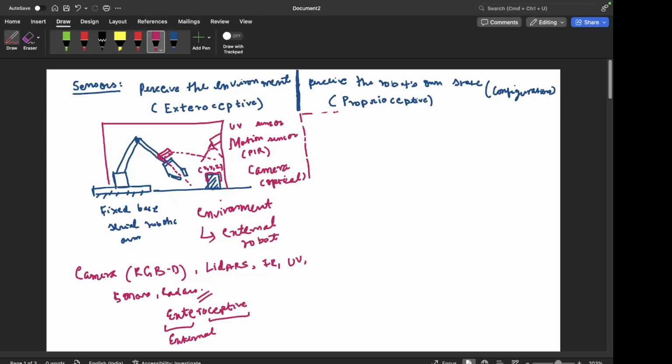You're saying it can do without sensors also. Okay, yeah, that's one option. What you can do is calculate what are the angles that need to be commanded to the motors, and you just command those angles to the motors, and you hope that the motors are accurate enough that they move precisely that amount, and you hope that your end effector is in a perfect position to hold on to that object.